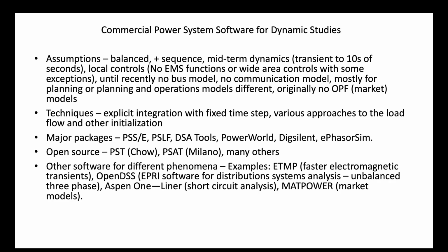The operators need to see the actual substation layouts, which means the bus breaker model, what the protection looks like, and where the connections are, because you can have a split bus. As soon as you have a split bus, then you've got a different sort of load flow, a different sort of state estimator and so on. There's no communications model.